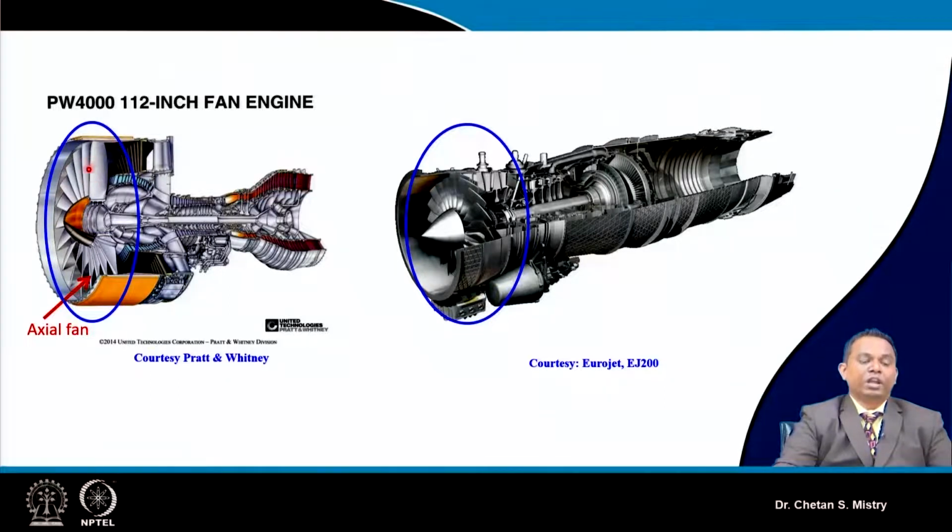So here in a small region we will have the flow be transonic, or we can say supersonic. So we can say this fan is a transonic fan. Okay. Now here this is the Eurojet EJ200. As we have discussed, our expectation is to have compactness and light weight, and if we configure this as a special requirement for, say, military application, under that condition you are supposed to rotate your fans or LP compressor at high